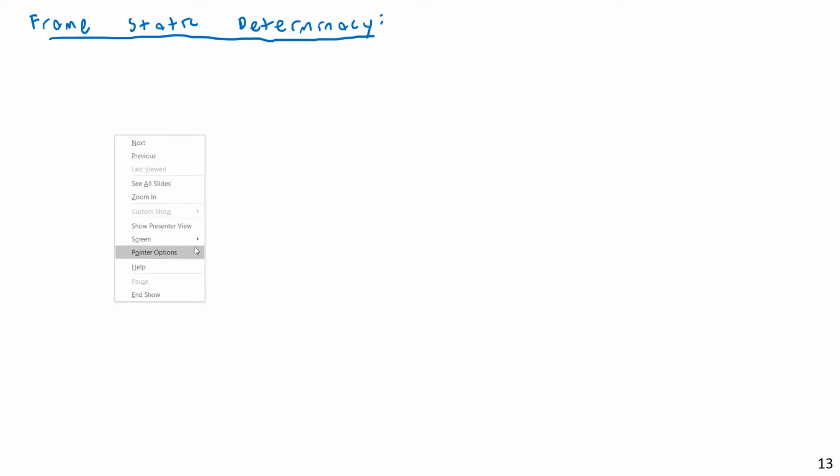How do you determine, before you start running through a whole bunch of equations, whether you're going to get lost in those equations? Well, hopefully you're doing the math right. That's one way to get lost in the equations. But another way is if the frame itself is statically indeterminate. If the frame is statically indeterminate, it doesn't matter how good you are at your math and your engineering, without using things like mechanics of materials and elastic theory, using just statics alone, you're not going to be able to solve for all those member forces. So how do you know if a given frame is statically determinate?